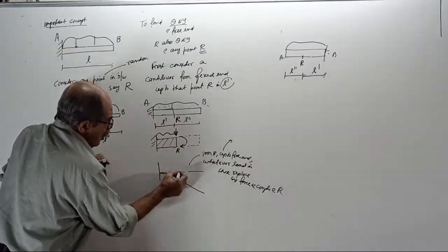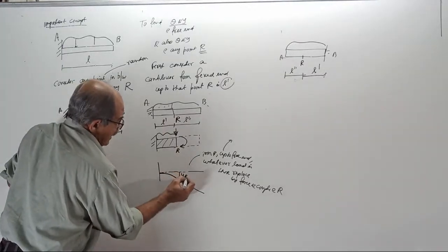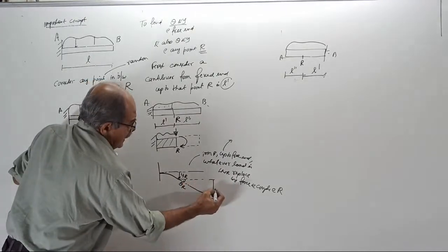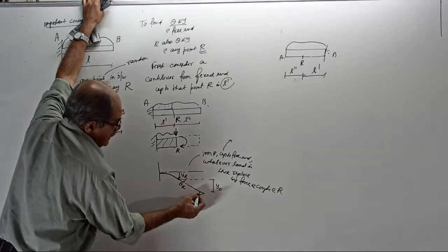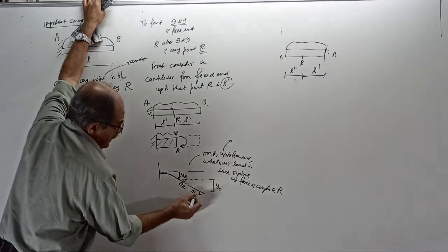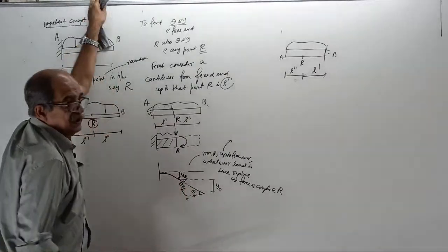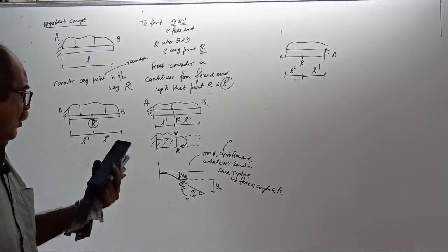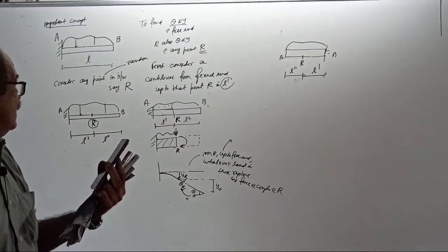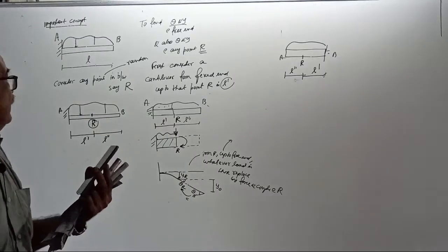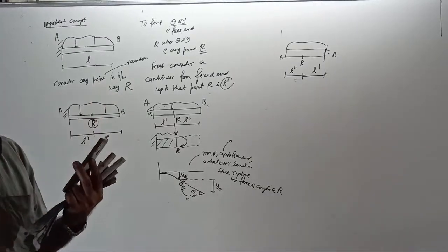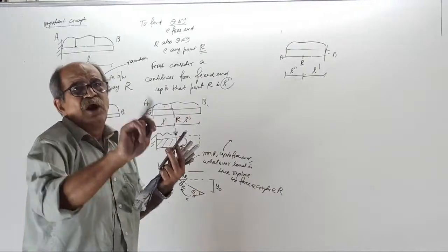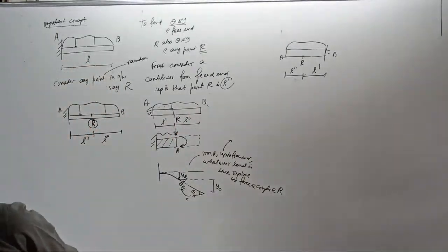Now you know how to find deflection at R, and also you know how to find theta R. Then this is the extra deflection y naught and theta y naught. This is theta at B equal to theta R. This is already over yesterday. Yes or no? Fast. This concept: to the right, to the free end side, whatever load is there, its effect is transferred here. Now, the remaining free end, don't consider loads. Okay. Now, you get the answer.